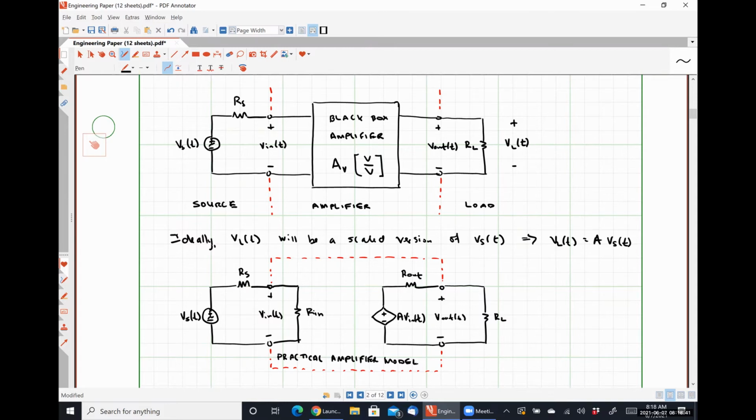If we had an impedance amplifier, we'll still have a voltage source. If we have a transconductance amplifier, it's a current source. So depending on what our output signal is expected to be tells us whether or not we're going to have a dependent voltage source or a dependent current source. Not particularly important now, but when we get into our transistor circuits and simplifying them, it'll be very, very important,